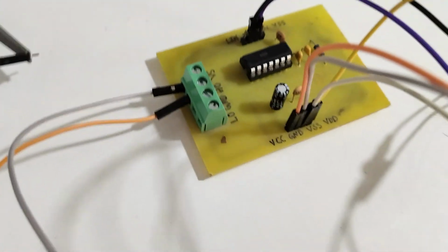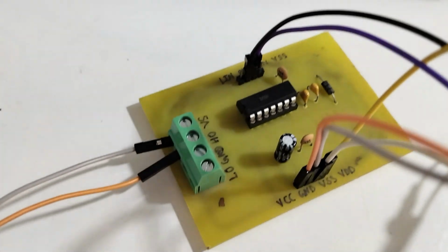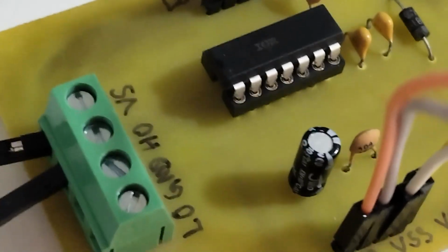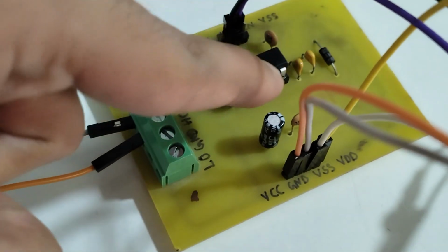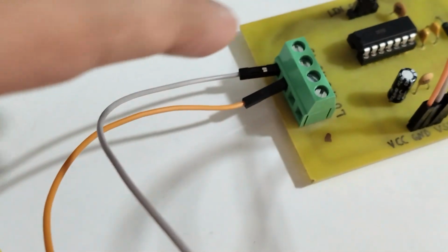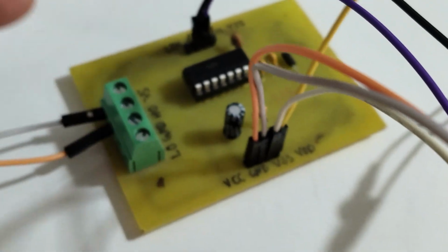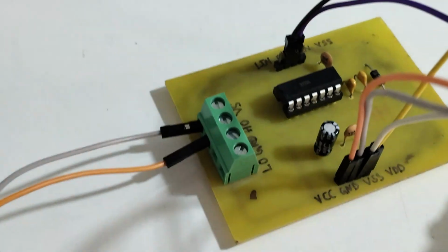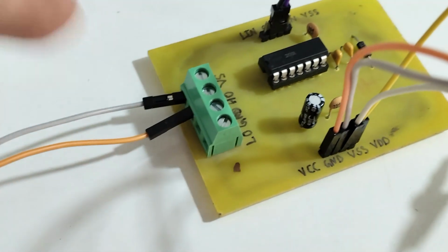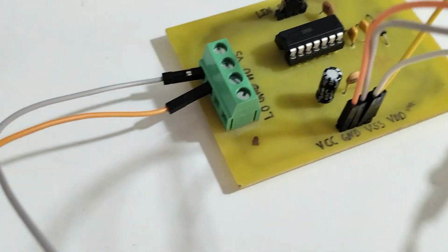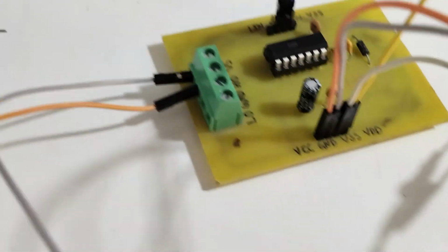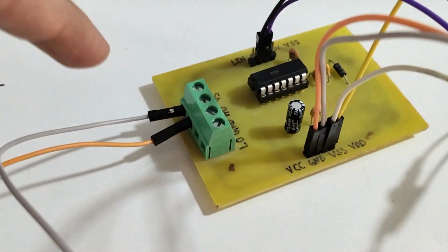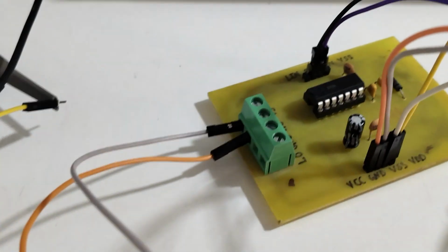And after that, that goes to our IR2110, and as I said, I made a small PCB for that. I etched it myself. So we have it housed over there. That's the IR2110. We have a few bypass capacitors, and this is the bootstrap capacitor, the bootstrap diode, and just female headers to give the inputs, and screw terminals to take the output. And screw terminals are nice since the peak currents can go a bit high, as you can see, to drive the gate. So screw terminal is better than a female header here. And try and keep the traces short, since even a small gap increases that inductance.